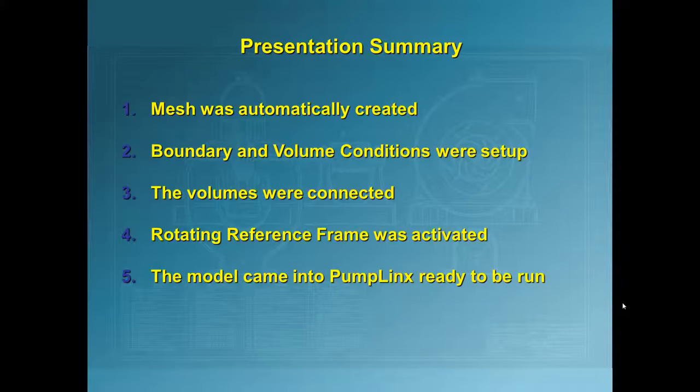In conclusion, to summarize, we exported a blower created in CFturbo into PumpLinx and saw that it was all ready to run. The mesh was automatically created, the boundary and volume conditions were set up, the volumes were connected, and the centrifugal module as well as the flow and turbulence modules were activated, and the centrifugal module automatically put the rotating parts in the rotating reference frame as required.